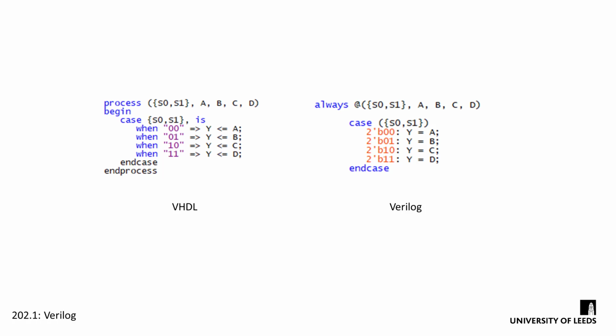Similar to the differences between procedural programming languages, the two HDLs perform the same or similar functions, but have different sets of rules, syntaxes, and structures. In this example, I've described a simple 4-bit multiplexer in both Verilog and VHDL, so you can get an idea of the differences between the two languages.